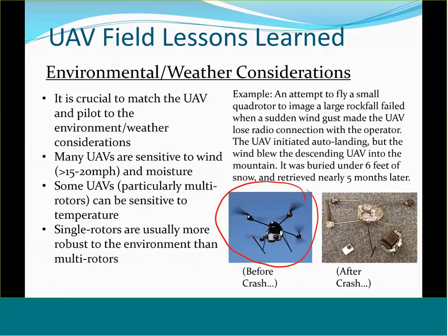Where we were standing watching it, it was fine. But you have to consider where the UAV is flying, not where you're standing. And the wind gust pushed the UAV back behind a large boulder, and we lost radio connection with it, which initiated the automatic landing sequence for the UAV. Unfortunately, it tried to land itself on the side of this rock fall and crashed and ended up getting buried under 6 feet of snow for nearly 5 months.